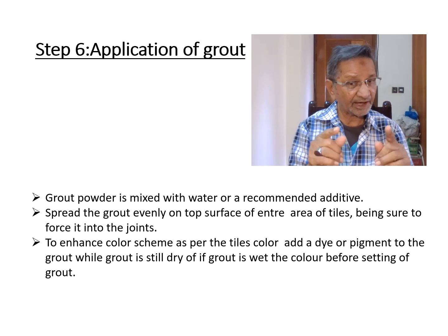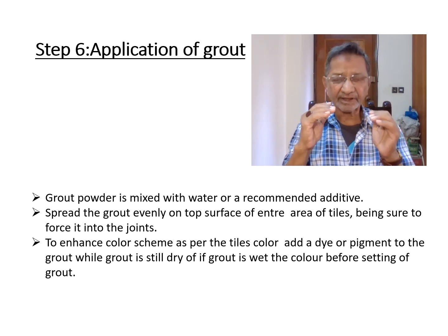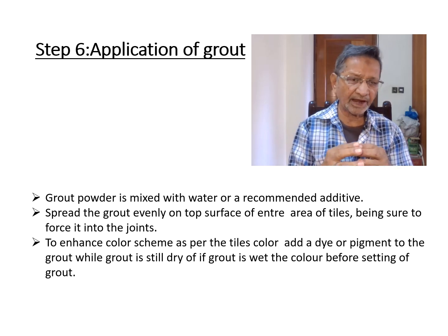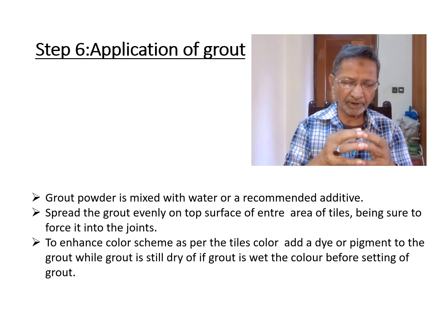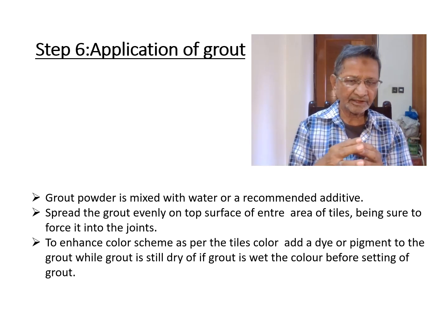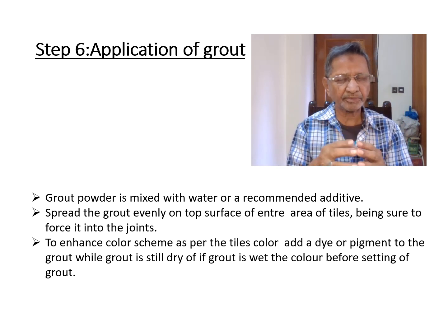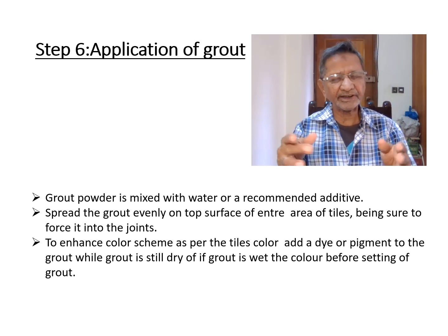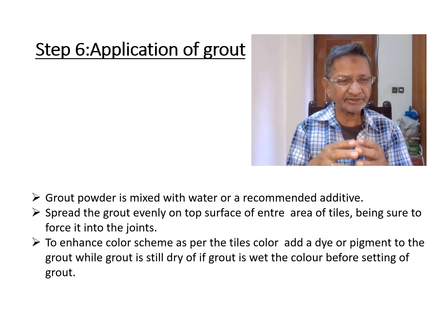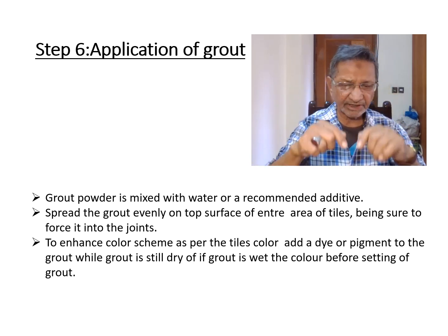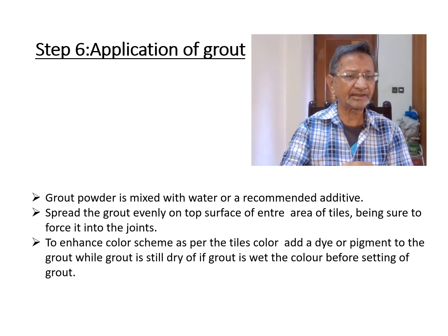I mean, when the tiles are installed and until the grout is applied, you have to cover the tiles with polythene sheets or any other way so that dust does not accumulate in the joints. If it is accumulated, you have to remove the dust from the joint so that the grout goes up to the bottom of the layer of the tile.